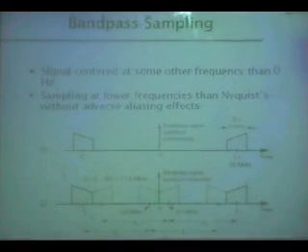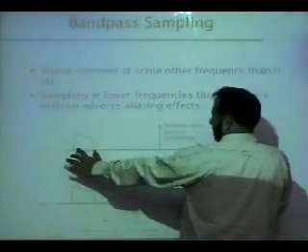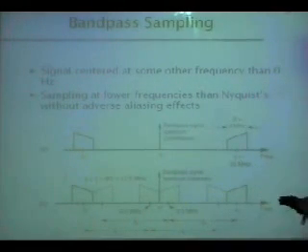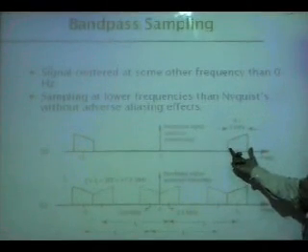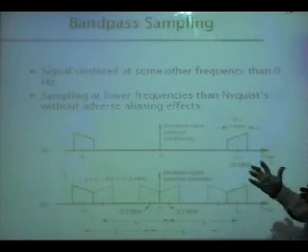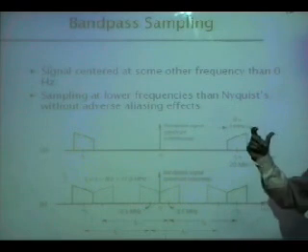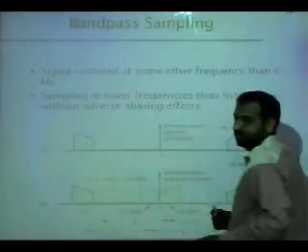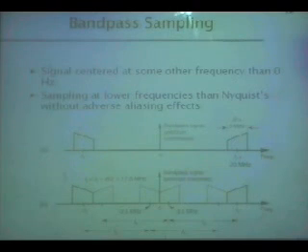And this is about the band pass sampling, which I have covered. You have bands further apart, but the spectrum is clean. There is no out of band noise. There is absolutely no reason for you to sample it at a very high rate. You know the band, you sample it at a very low rate, and there are ways of knowing that. The formulas will be covered in the next lecture. And then you will have copies everywhere. You will get a lot of copies, because once you alias, it depends how much you alias.